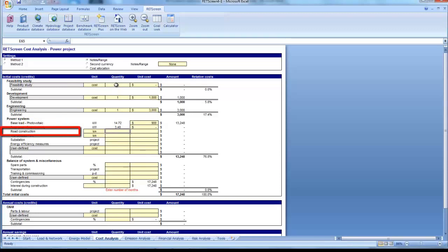An access road for construction and an ongoing service road are normally required for a medium to large-scale power project. Since this is a small project being developed on an established site, no road construction is expected to be needed. The transmission line cost is site-specific and depends on the length, type, voltage, and location of the line, and the installed capacity of the power plant being developed.